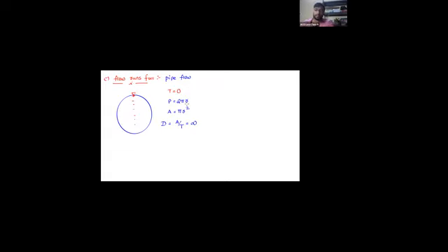My dear students, here the hydraulic depth will not be applicable in the case of pipe flow. Hydraulic depth can be used only in the case of open channel flow, because in open channels there is a free water surface, and when there is a free water surface there is a top width, whereas in the case of the pipe flow the top width is equal to 0.